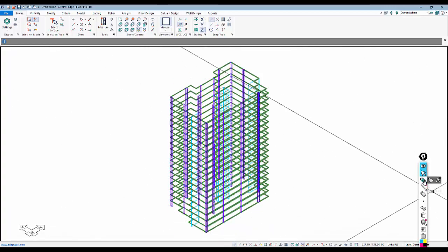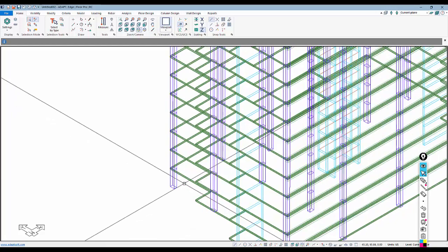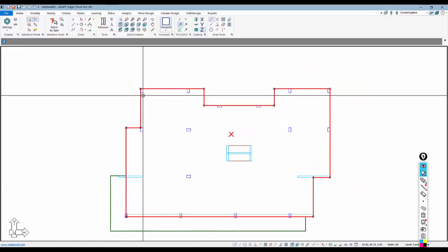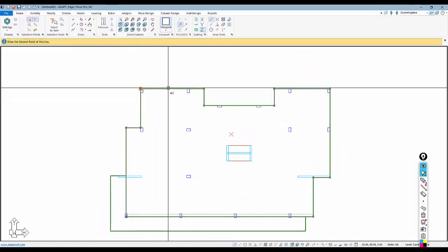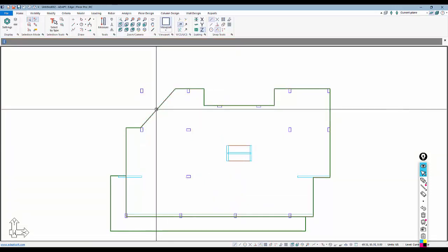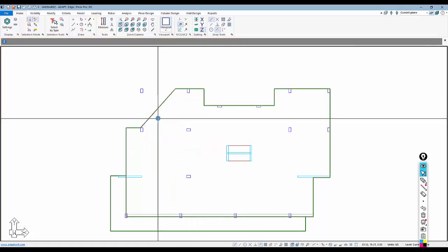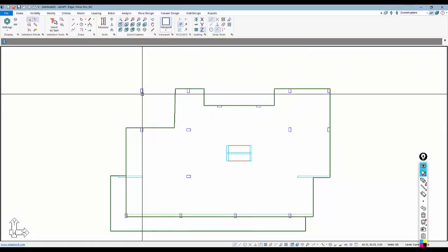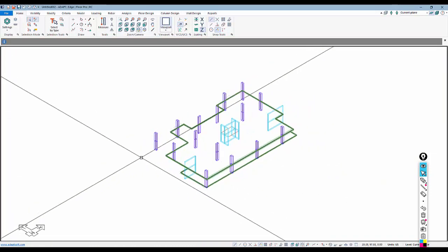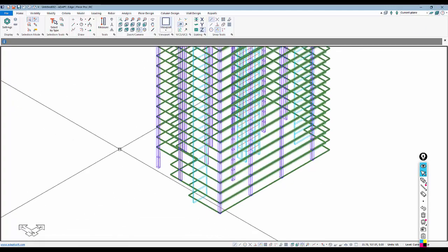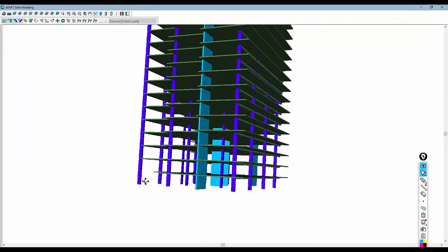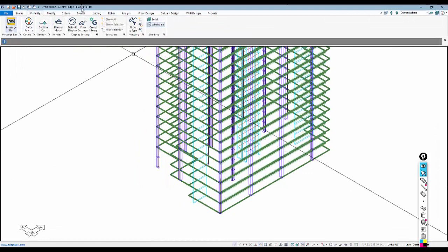For example, if I have a situation where, I'm actually going to show this, let's go to this level, and I'm going to move this along this line to here. Let's do that movement, and then I'll insert a vertex here, and I'll just square that off like this. So this column here really becomes a double story or a double height column. If I go back to multi-level mode and let me check that in the rendering, you can see that condition right there.